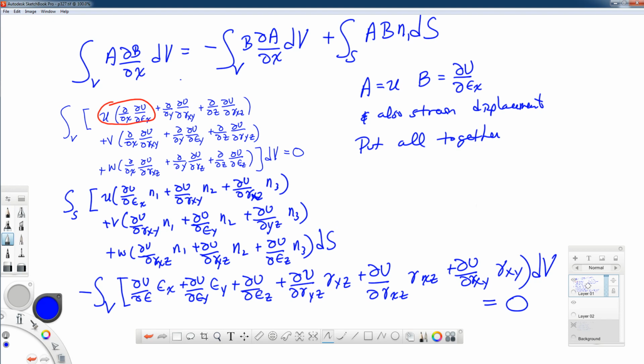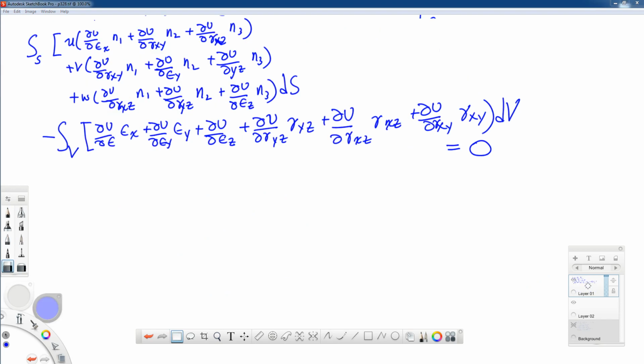Alright, there's another thing that can happen, is that the stresses from the little u, v, and w, if those are prescribed, the stresses are prescribed, the tractions on the surface S, those stresses from little u, v, and w will also vanish, because u prime, v prime, and w prime, u double prime, v double prime, and w double prime give the same solutions. Alright, so let's write a little bit of that down. Let me put the equal to 0 up here somewhere.